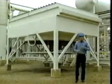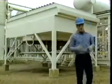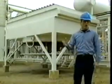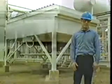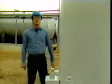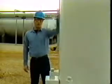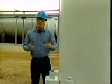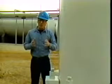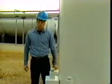A trim cooler is used to lower the temperature of the lean amine solution coming from the surge tank and control the temperature of the lean amine solution going to the contactor column. The contactor column. That's where the process starts all over again. Sour gas enters the bottom of the contactor column, while recycled amine solution flows down from the top. Recycling the amine solution is a key point of the sweetening process, and in fact, the main purpose for most of the equipment in an amine sweetening unit.